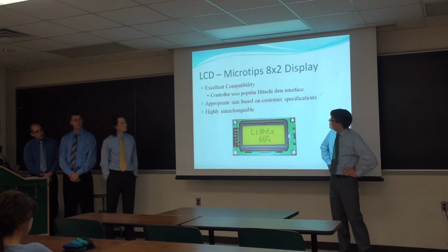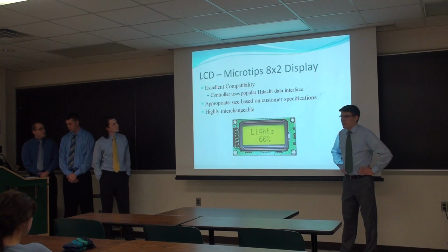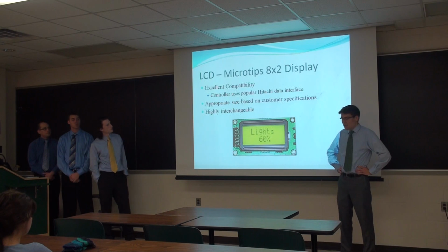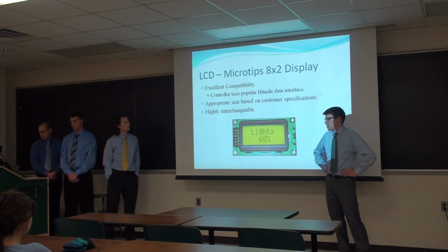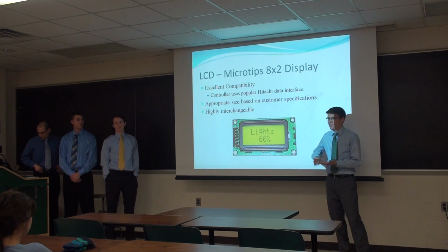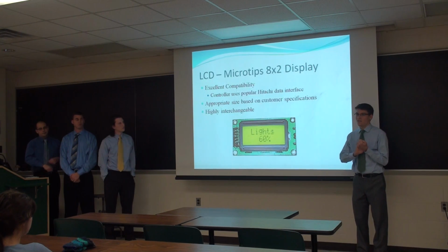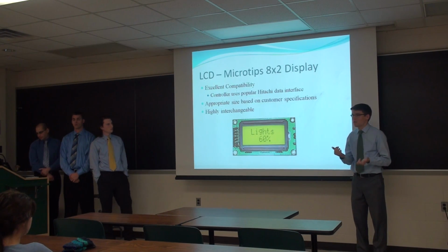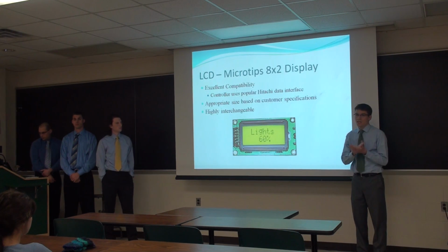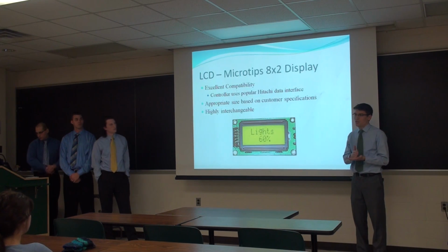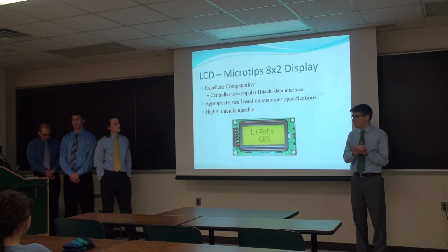For our LCD, we're using a Microtips 8x2 display. The main design parameter that motivated the selection of this display is the fact that it's highly interchangeable. It uses a Hitachi driver. It's actually a Samsung driver, this one, but Hitachi developed it. And it's a standard protocol that's interchangeable with a lot of other LCDs.